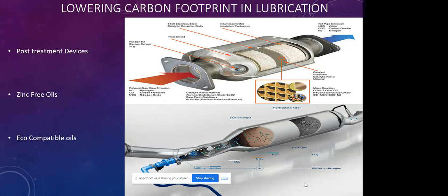Even for modern day engine oils, we have oils that run on SP specifications. These SP specifications we call eco-friendly. They are emission compatible, and they are designed to reduce the amount of emission that comes out from our exhaust. For industry, we are trying to limit the use of heavy metals in the blending of our oils and additives that are poisonous to our environment.